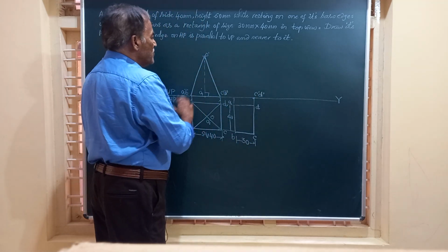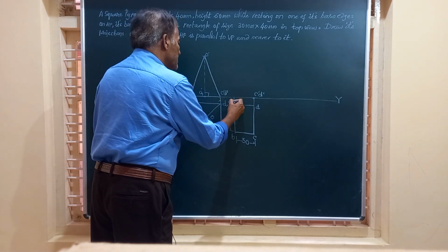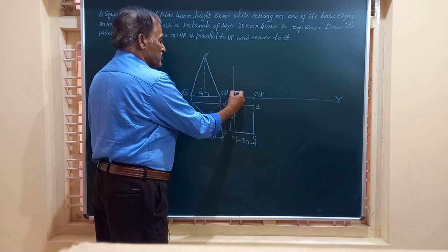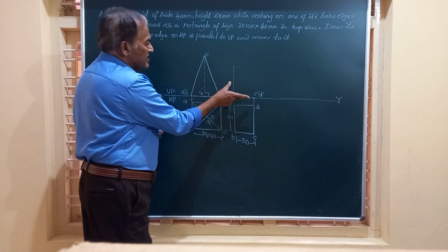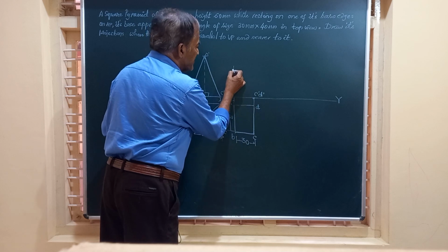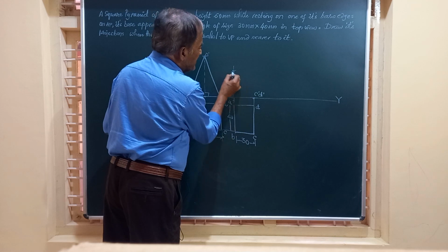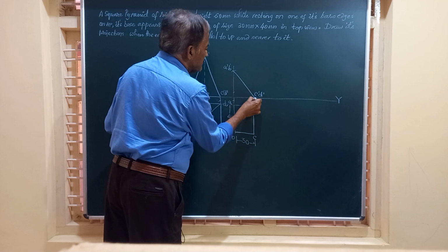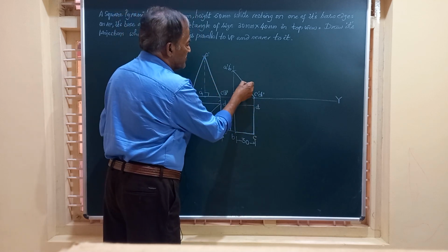And friends, how to obtain this figure here? You know, you have this side AB. You can draw a thin vertical line passing through that. And now friends, the base has got a dimension 40. Taking C dash as center, C dash D dash, and radius equal to 40, I just draw an arc. I join that and obtain the base. So the base of the solid is here. This dimension is exactly equal to this.